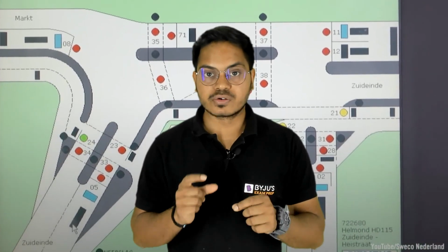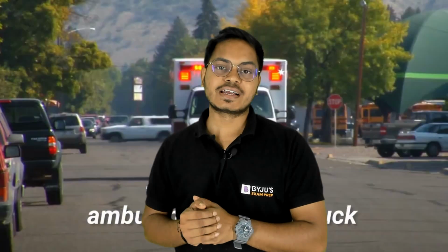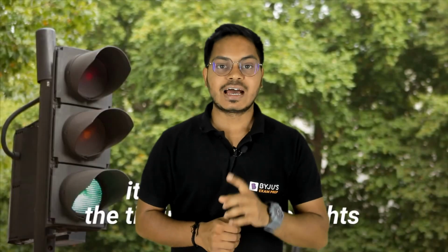And then there are vehicle actuated control, VAC, traffic signals, which are going to analyze the length of the queue, and according to the volume of the traffic they are going to provide the green light, amber light and the red light, which actually reduces the loss of time of all the road users and provides the optimum level of the traffic signal design.